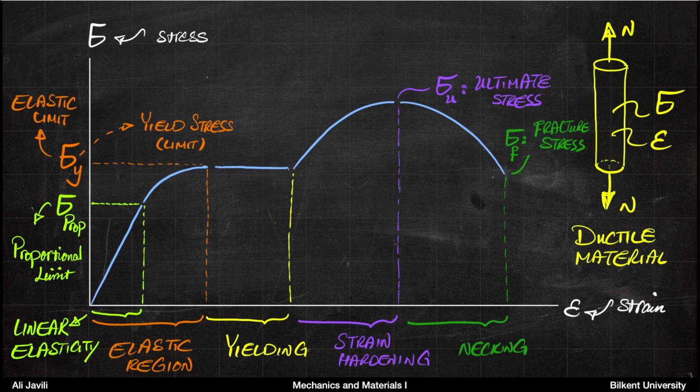So what is happening is basically related to the definition of the stress as we spoke before. If you remember, stress is the normal force divided by the area zero, or reference area, or area at the beginning of the test. We call this stress maybe the engineering stress, or nominal stress if you want.